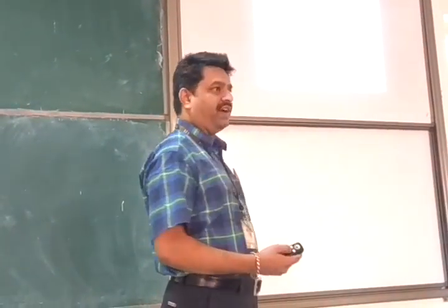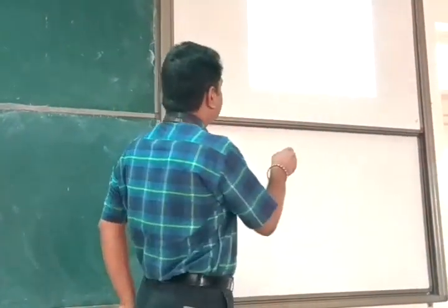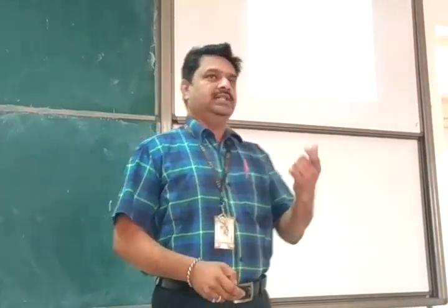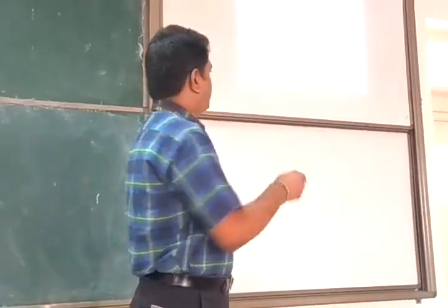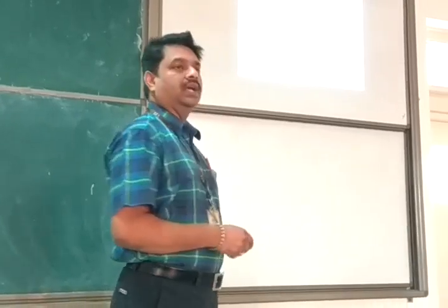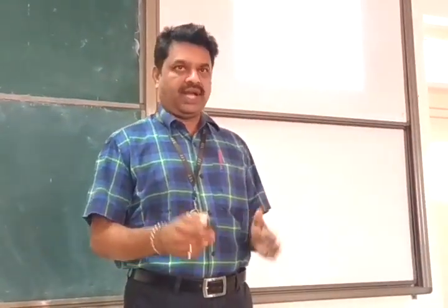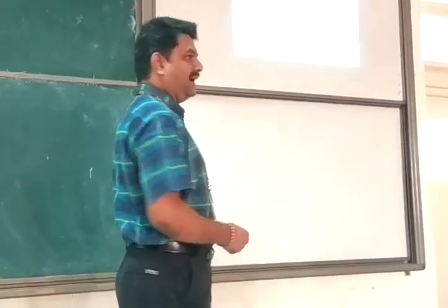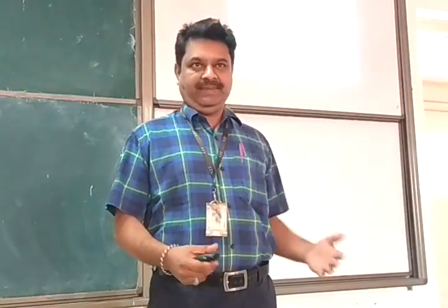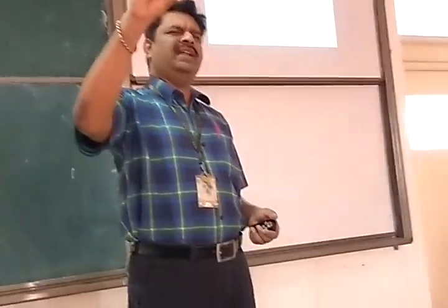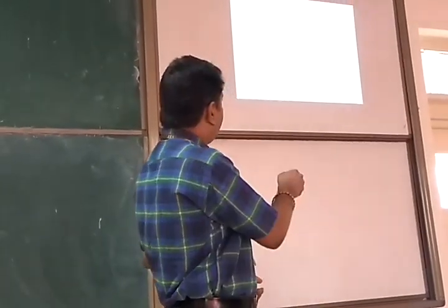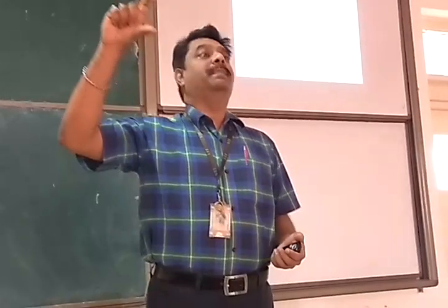And when we take such large measurements, we also quantify the standard deviation. Standard deviation is the amount of uncertainty that is attached to that measurement. So its standard deviation, 0.026, is the uncertainty in that particular measurement. To that extent, it will vary. It's a spread. The spread of the measurement is so much. So mean and spread we will say, so that you will have some idea. Oh, the diameter is this on average, and minor variation will be there. If the standard deviation is big, average is this, there is a bigger variation in the diameter.